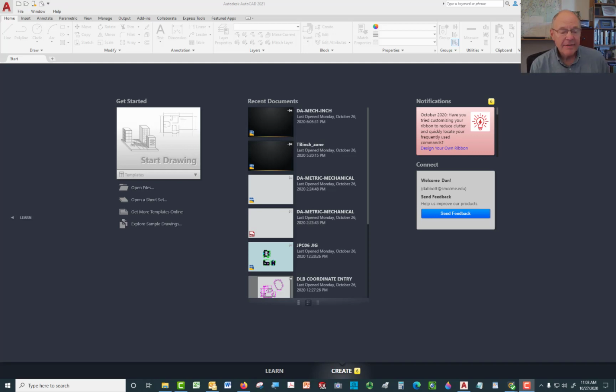First we have to make sure that whatever we draw is going to fit into the sheet size that we are going to use. Since the sheet size is determined by the plotter, and the printable area on a specific sheet is also determined by that plotter, first we're going to look at a plotter and make sure we have an idea what dimensions a border can be, and then start from there. So we're going to start a drawing.